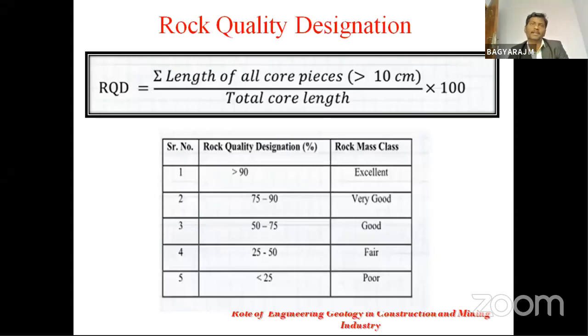So what exactly is RQD, and what is the perception behind this parameter? The closer you have joints, the more shear zones are present, and core recovery as well as RQD is very low. That tells you about the condition of the rock deeper in the ground, so RQD is going to be very important for these aspects.